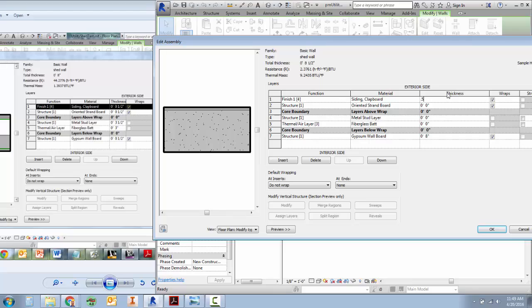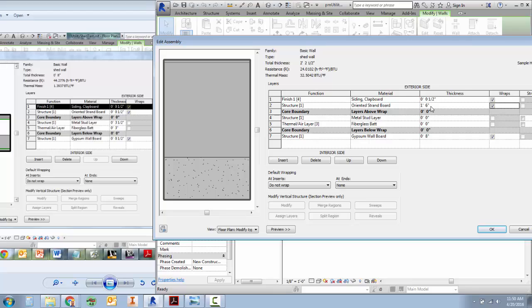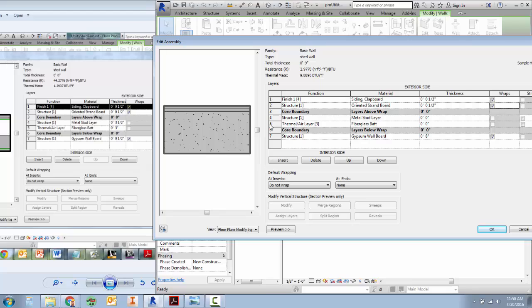You can also type in 0.5 inches and it'll automatically convert it to 1/2. What you do not want to do is type in 0.5 and hit enter. When you type in 0.5 and hit enter, it's assuming you're talking about 0.5 of a foot, or a decimal foot. If I type in 1.5, it's going to give me 1 foot and 6 inches, the decimal equivalent of 1 foot 6 inches. So if you're looking for a 1/2 inch, you need to type in either 1/2 inch or 0.5 inches. Either one will get you the answer you're looking for.